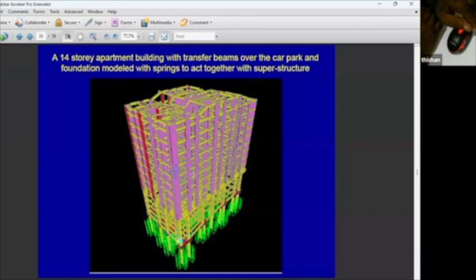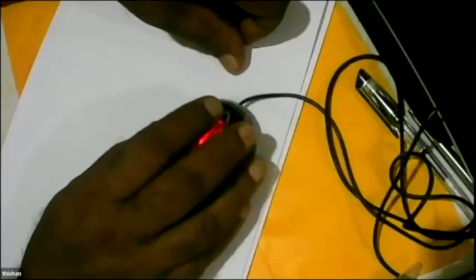When you are applying a load on a beam, the general expectation is that we'll apply the loads on the center of the beam, so the beam will not be subjected to high torsional moments. But what has happened in this particular instance is that we have to extend the building to the very edge of the transfer beams. Because of that, the loads are not acting on the center line of the transfer beams, but on the edge. So let's see what the repercussions of that are.